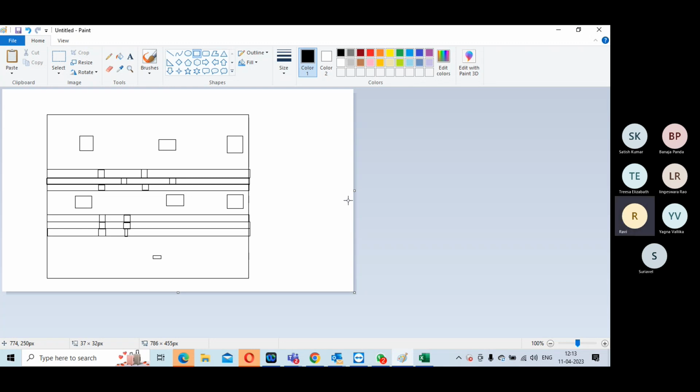We're placing the modules based on frequency. But you are not creating fly lines for modules? For macro placements, we place based on fly lines? No, the first thing I told you, macro placement should not be based on fly lines. It should be based on your data flow diagram, or you can look at your module hierarchy and accordingly which macro is supposed to be in that hierarchy.